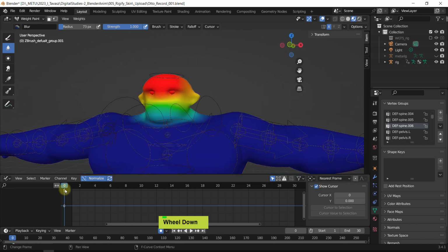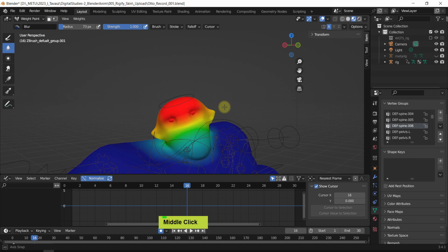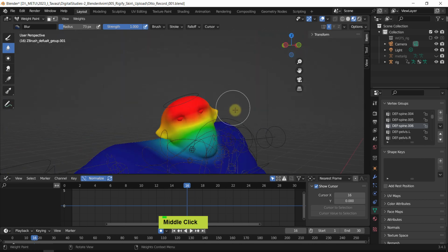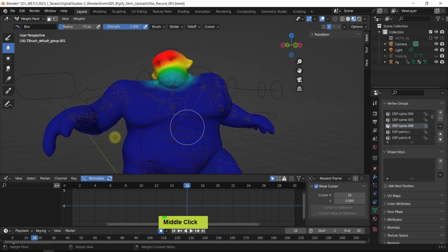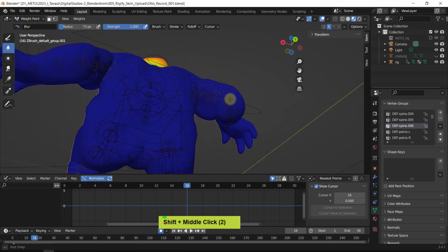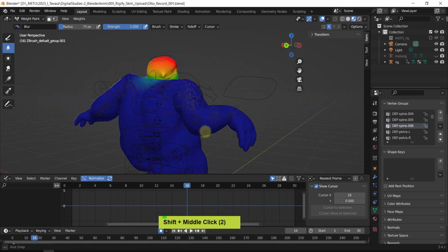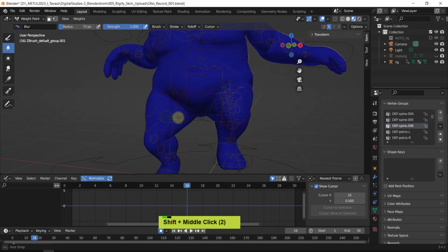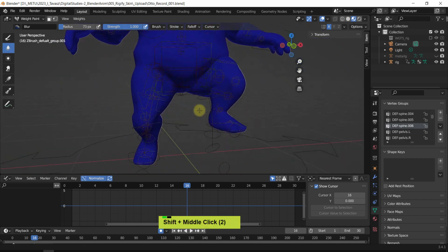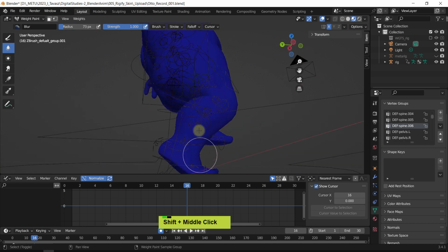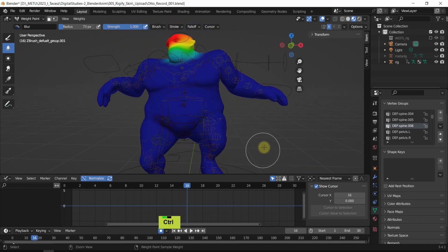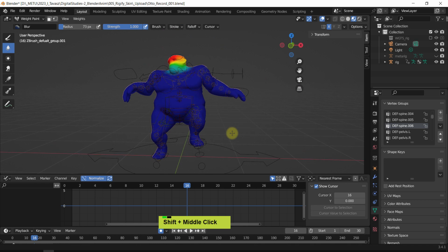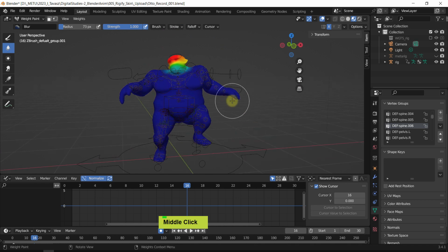Okay, so here we are. Let me test this. All right, working fine. Eyes are there, and the top part of the face is not stretching too much. Let me look at the elbows. We have some natural looking deformations. Even if it's not 100% perfect, it's fairly good compared with an average weight. I think it's a good result. So Blender is good at this. It's not really good if you have multi-part meshes, but it's really good if you have a single watertight mesh. All right, that's it.